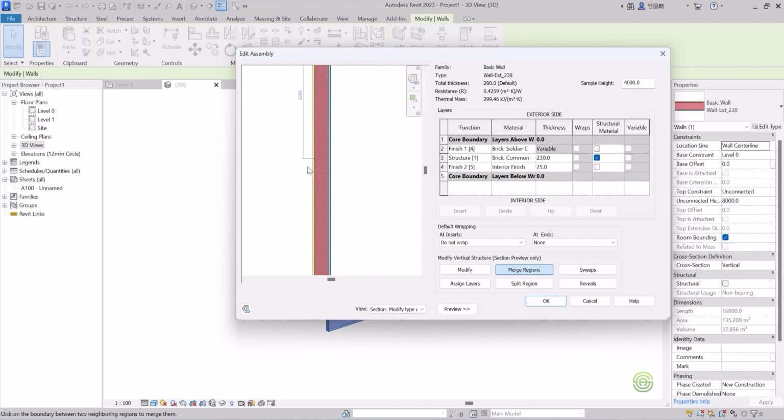First, we have to split by two split marks. Once you have two split marks, just type the amount which you want to give to one side of this dimension. After setting one side of this dimension, at the below, if you want to give the equal dimension, then you can do it by clicking on merge region. So by that you have merged these two split regions.